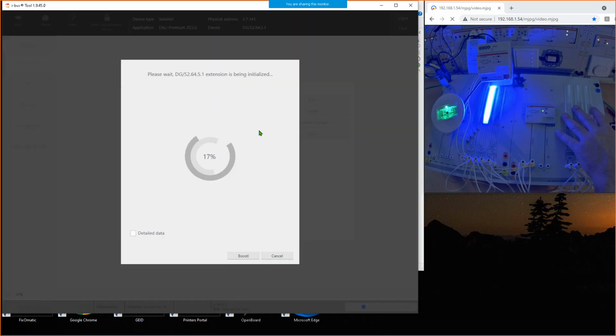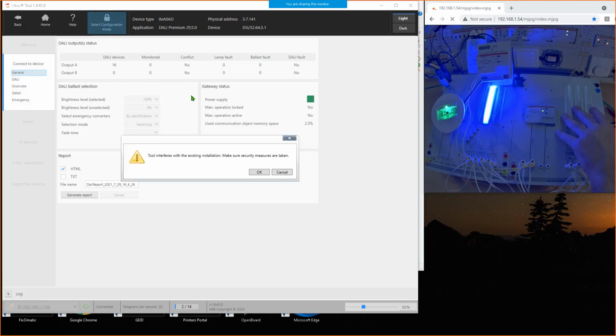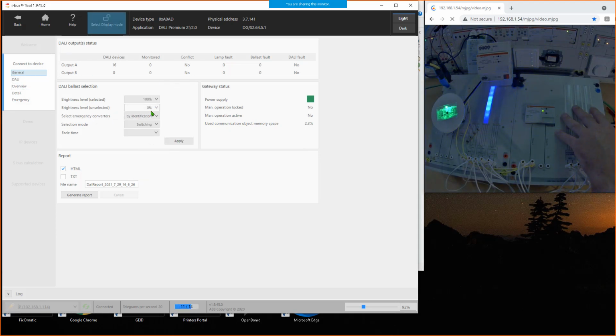The advantage of this new parameter unchanged is if you have a running project and you have to replace a ballast, or you want to do some tests or maintenance, then the other ballasts are not affected. So when you have an open office, for example, the people in the room have no influence by the light, because all other lights remain in their actual position. Okay, good. This is, I think, a very nice parameter, unchanged.